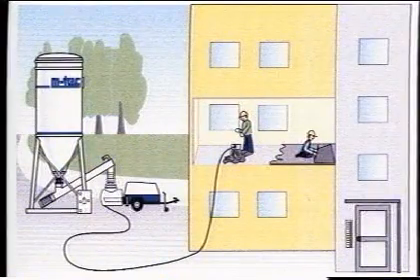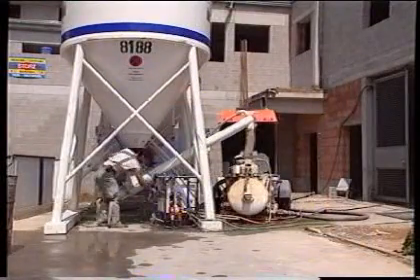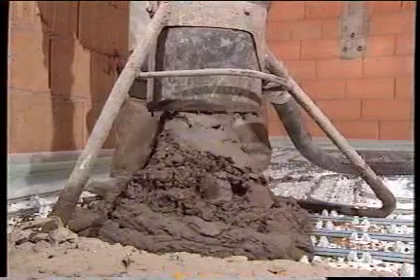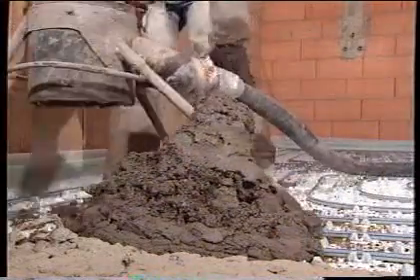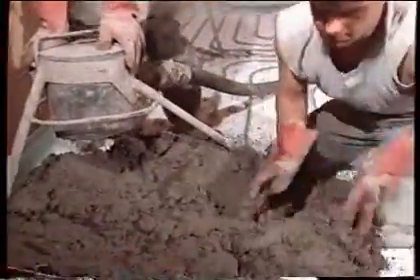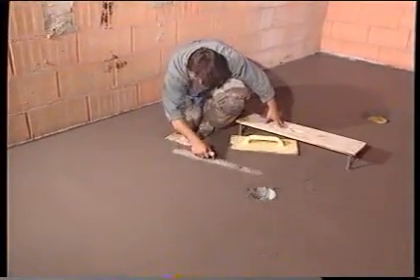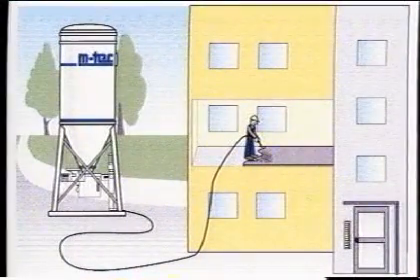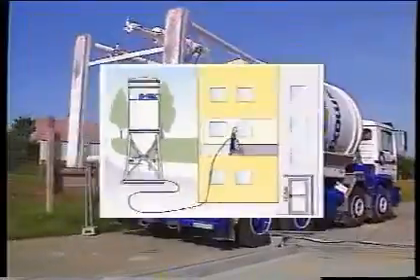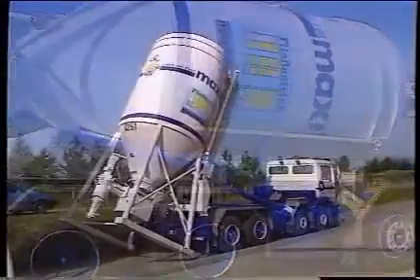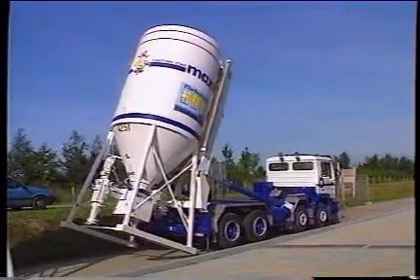Another application for dry mortar is floor screed. In the conventional method, a floor screed machine must be fed, and this conveys the material in its damp condition to where it's applied in a somewhat laborious procedure. A much more rational system is the innovative method of transporting flowing screed as a dry mortar product by means of the m-tec transporting and conveying system to its point of application.